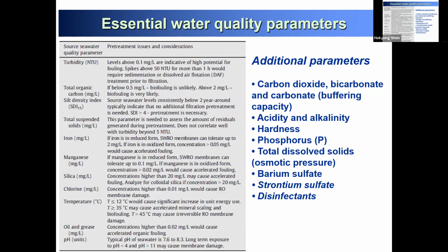We have to use an average temperature rather than a summertime design, since winter time would be less workable. So when you design, say we want to design for 20 degrees average water temperature. This can give more buffer, and in winter time and summertime you will have a good flux, even across 4 seasons.